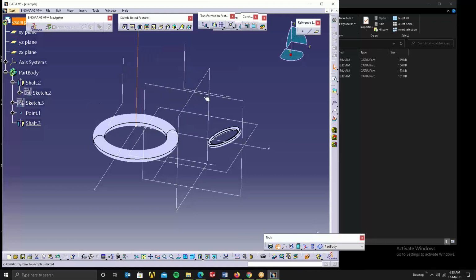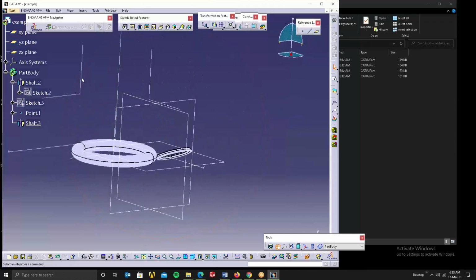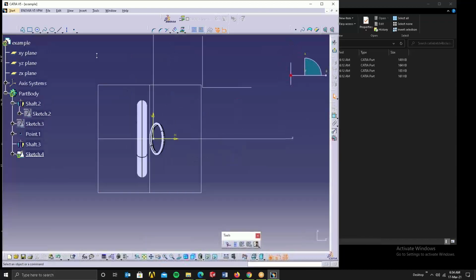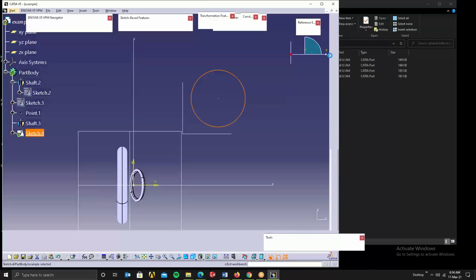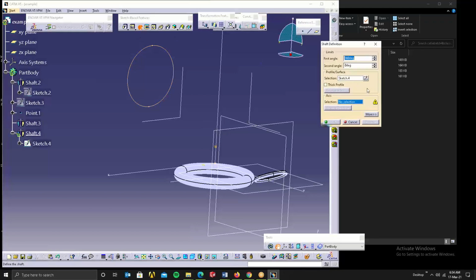It's not required. And one more advantage of this is, see, you have these L shapes, right? These are actually planes. Usually we have this datum plane, right? We replace this with axis systems because we can use this plane as a sketch plane. I can just click here, go to sketch, and sketch on that surface itself. So you can revolve it.